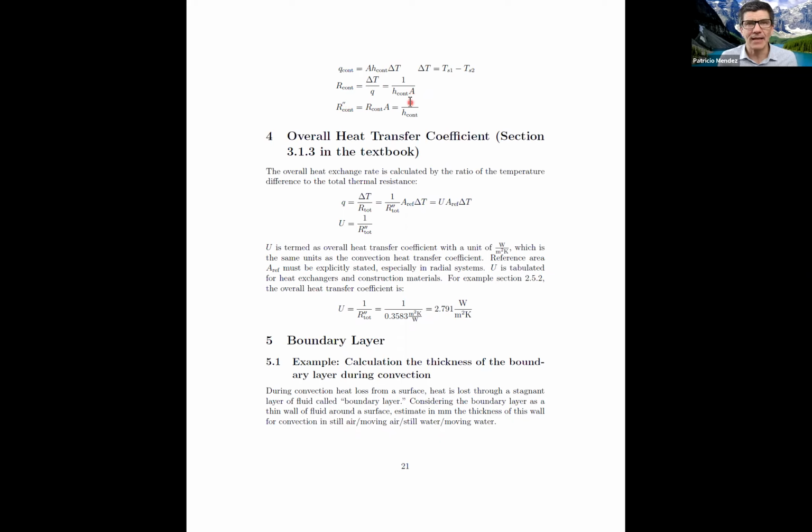But now this enables us to use the concept of contact resistance even when we don't have convection or radiation, but just contact between two solids. We can do so much now. We can have a solid that has paint and is in contact with another solid that has paint, and now we would have thermal resistance of a solid, thermal resistance of the paint, thermal resistance of contact. You tell me what you want to account for, and now we can. This is awesome.